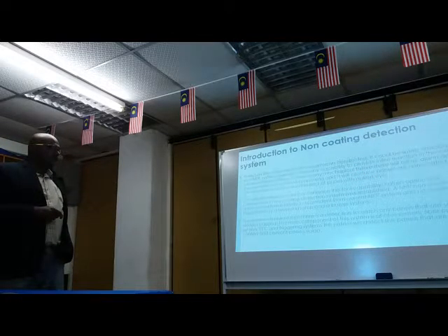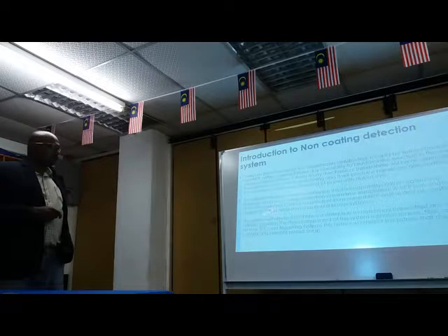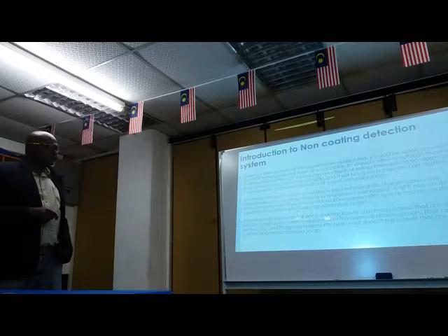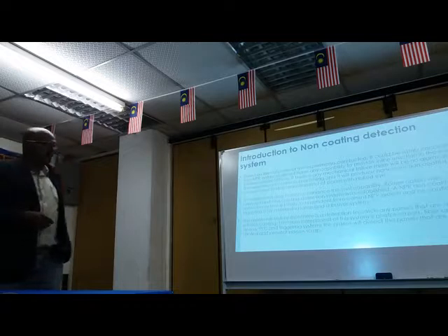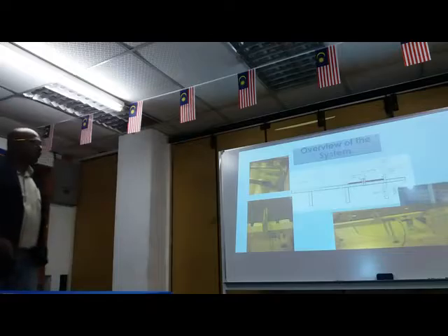To mitigate this and further enhance the tool capability, a Kaizen option was explored and the non-coating detection system was established. The NPR non-coating detection system is totally independent from the current NPR system, and the no-coating trigger is a revolving lamp and a buzzer system. The system will ensure that there is a detection to catch any panels that are sent without coating. The main components of this system are photo sensors, fiber optic sensor, and triggering systems, and this system will detect the panels that are not coated and prevent panel scrap. Okay, this is the overview of the system.